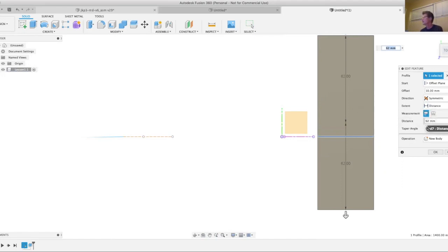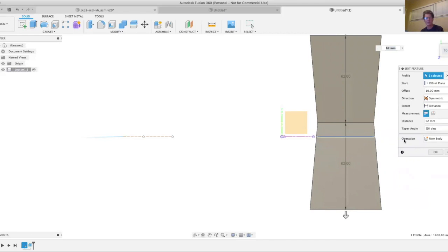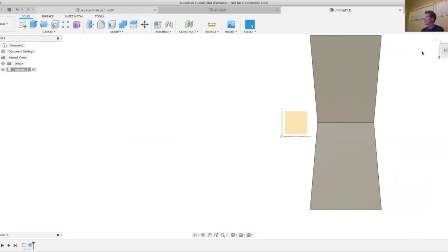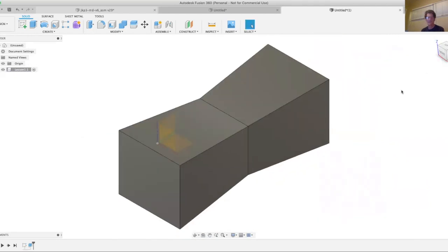Another thing we can do is a taper angle. And I think in woodwork, that's not so common. But if we're doing plastics, for example, or anything that goes into a mold, we often use what's called a draft angle so that the part will come out of the mold. So we can taper. Let's do a really extreme one here to show what it looks like. There's our taper angle, and it's tapering from where the sketch goes. Hit OK, close that feature, and there's our feature.